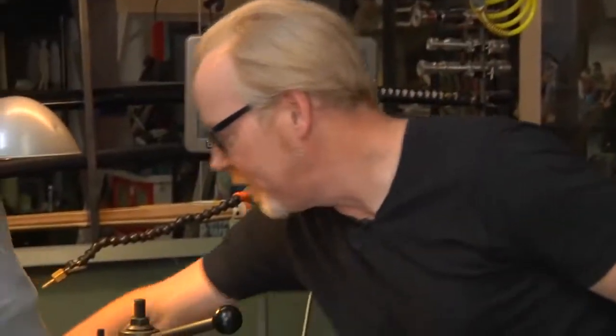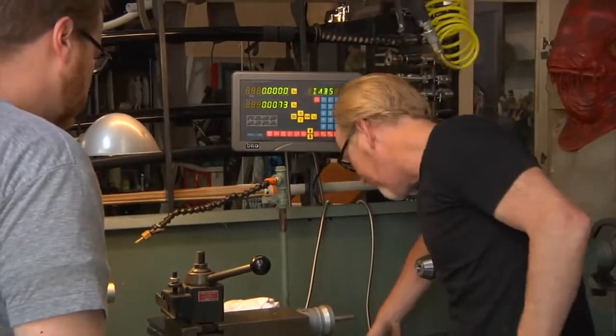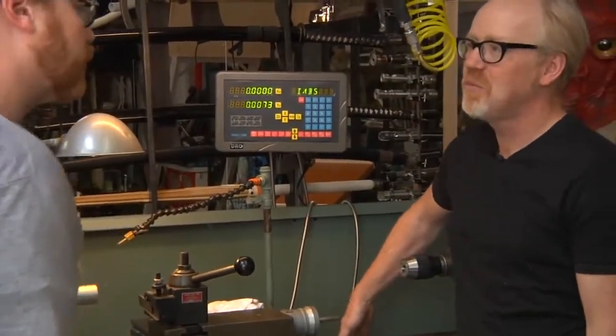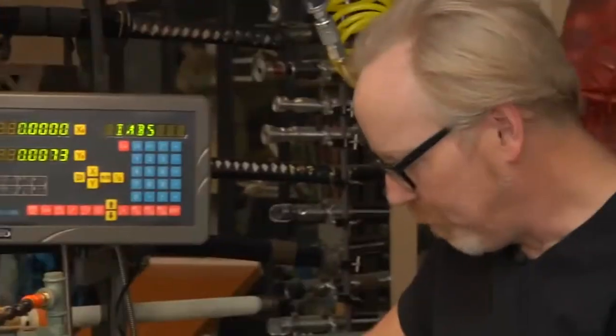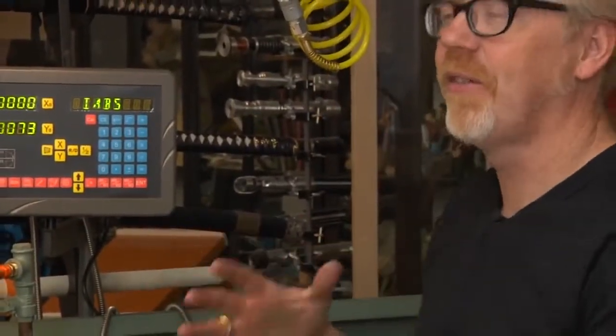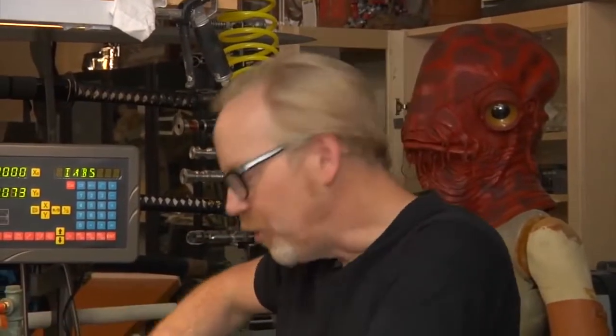Okay. So I put the 40-inch cross feed out here on the back, and it's actually bolted to the back. The nice thing about bolting stuff to machine tools is that while the ways and the key bearing surfaces are hardened steel, the rest is all cast iron. So attaching stuff to it, once you've clamped it in and got your positions right, isn't that hard. Plus, they sell the brackets for these with slots, so that once you get it close, you can use a micrometer to make sure you've really dialed it in.